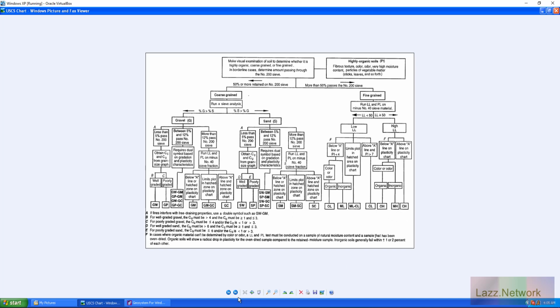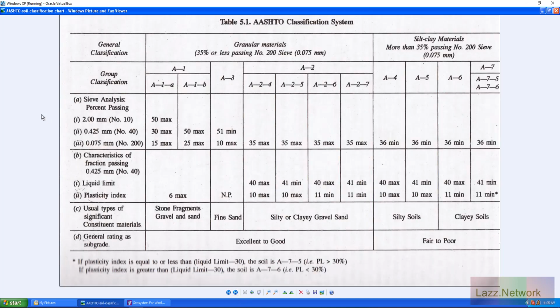That's the reason why that looks way more daunting than this here. This is only more difficult because there are so many different requirements, mostly with the sieves. I mean, granted, with the Atterbergs, it's the same thing, as we take a look here. So as we get back to our A2, we already know it's within 35%, but it's not going above 35 for our 200 wash. So for what's passing, okay.